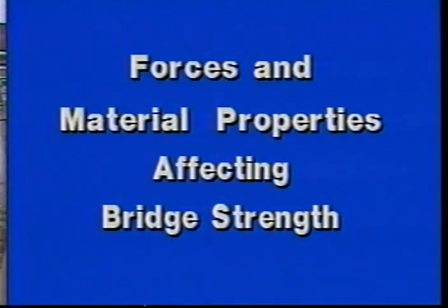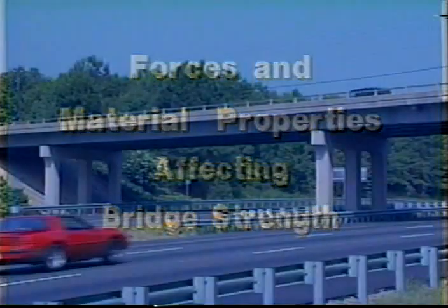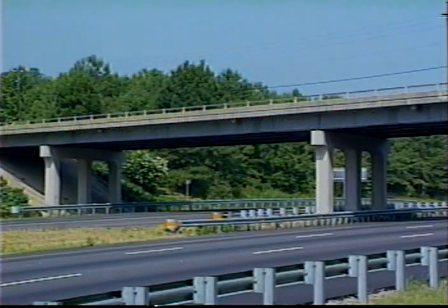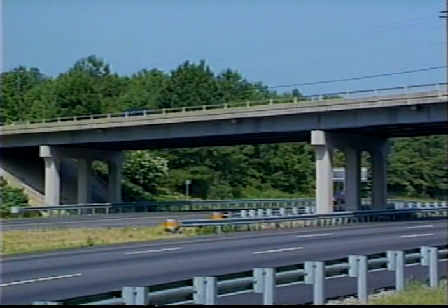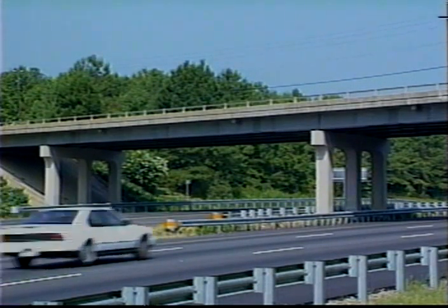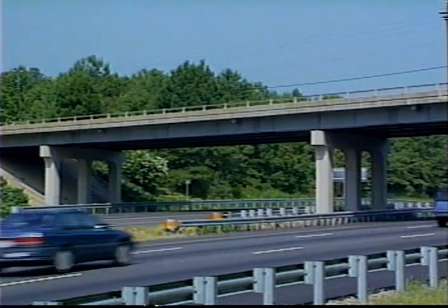In order to understand the importance of strength evaluation and load posting, a knowledge of the forces and material properties affecting bridge strength is important. Sound bridge evaluation must include an analysis of the forces or loads acting upon the bridge and the effects of these loads. Forces are classified as dead, live, and secondary loads.